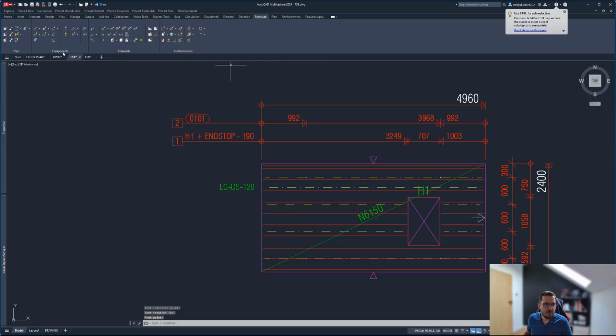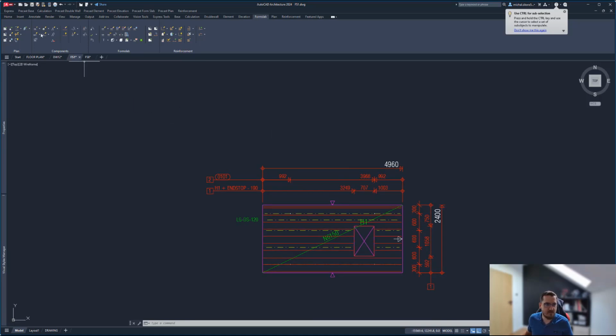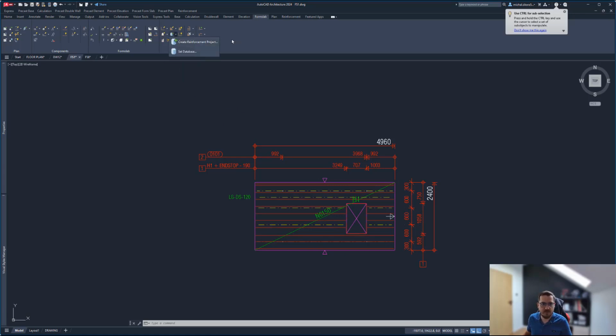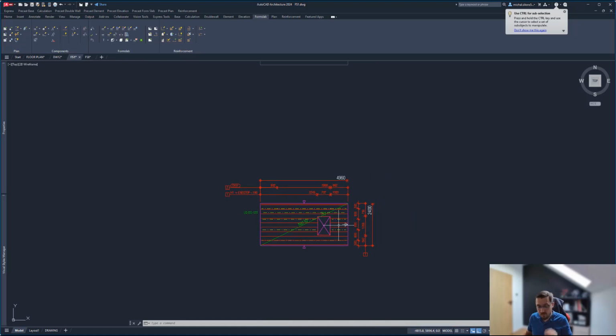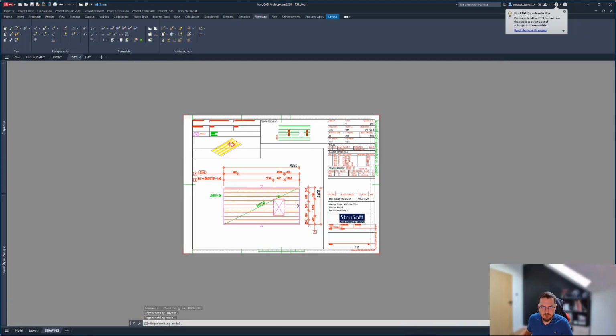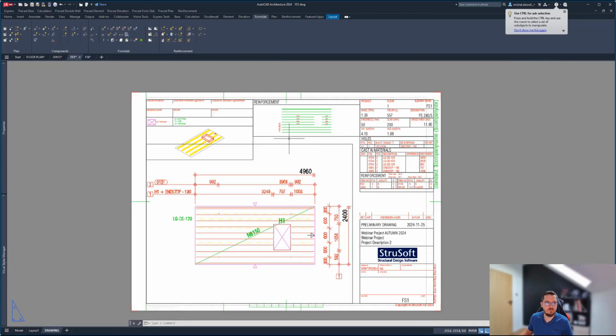And that's that. So we can of course add those girders, and they will be added to the schedule as well. So you can add girders here as well, edit those, save them to material takeoffs. Of course, for both double walls and form slabs, you can export the data format to Unitechnik and other machine formats, so they can be input into machines, and your meshes can be welded and bent as they are required. So again, go back to the drawing, and we have our reinforcement. If I refresh that girder, it would be there, and that's that reinforcement as well.